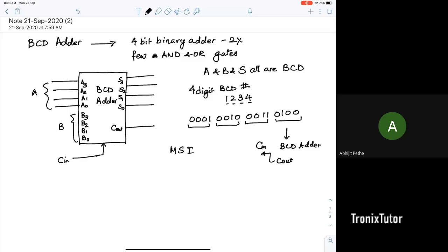So we're doing the adder. Now we'll talk about the comparator next, and then we'll do decoders, encoders, muxes. This week's labs will give you an idea as to how to use them. These are very powerful tools and used almost in all digital design. Anytime you pick up an architecture textbook or go into a microprocessor class next semester, this is where you'll start implementing. You won't start with truth tables and K-maps. You'd rather say, let me just take a bunch of decoders and implement the function I need to implement.